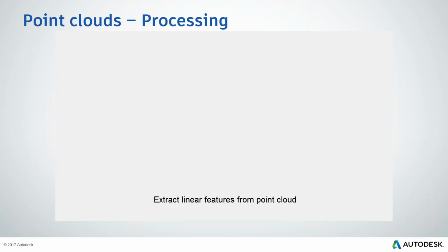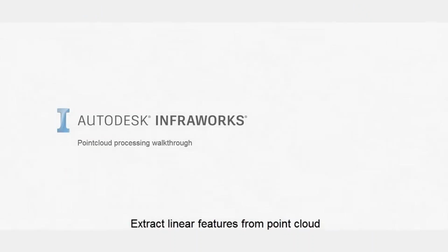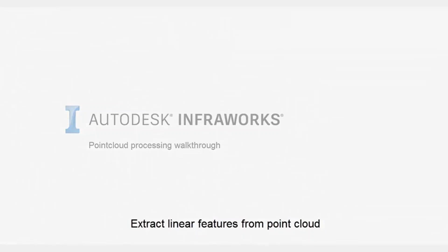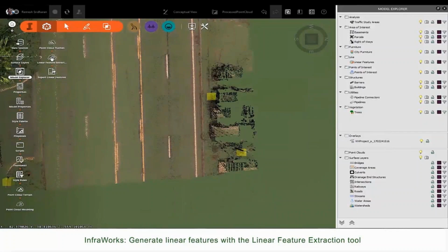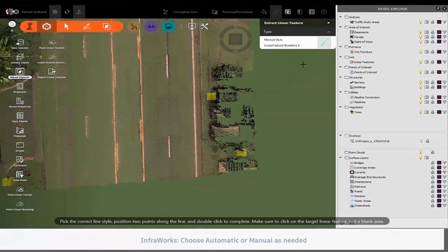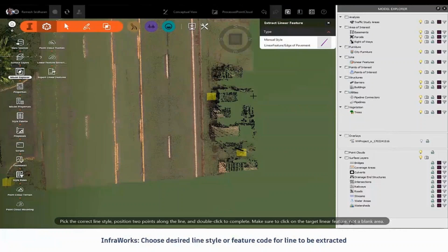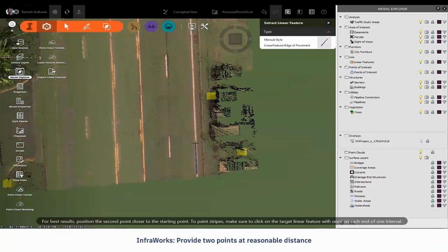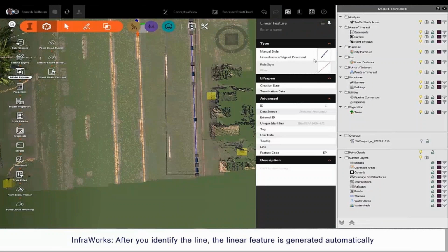Because if we are talking about, and we are going to the core of road rehabilitation, we have point clouds of the surface of the road. But as I mentioned again, it's millions and millions of points. So what we would like to have is what we call feature lines. So basically lines or 3D polylines, we call them feature lines, but we can call them 3D polylines, which are following, for example, curb, center line, edge of the road, and all this information.